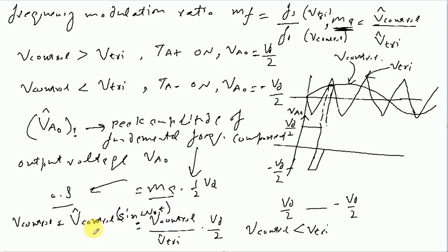This is how we normally write a sinusoidal signal. This is the peak amplitude. We have already established that the hat sign means the peak or the maximum value, and sine omega 1 t means the signal will have frequency equal to omega 1 in radians, or in terms of hertz it will be equal to this particular term.